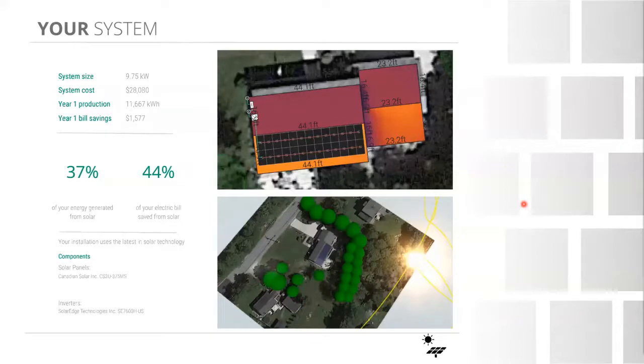And the other nice thing is design has been simplified. So for installers in the marketplace, or for anyone wanting to become an installer, these irradiance maps are built into software. So I can pick a house anywhere in Atlantic Canada, and the software will actually lay out my irradiance potential. This is the software you're looking at here in this slide, known as Aurora, and you're seeing the north-facing roof. It's purple, less solar irradiance potential than that south-facing roof where the modules are laid out. It also will produce shading reports, solstice reports, and more. It will do everything you need to do. So we don't have to get too involved these days in calculating production. Software will do it for us.